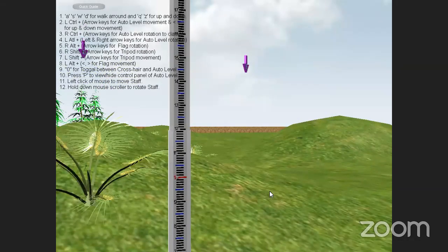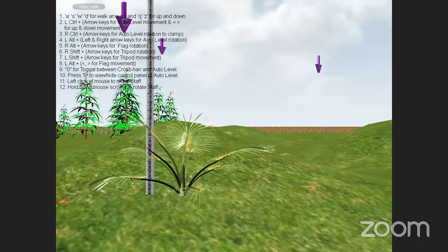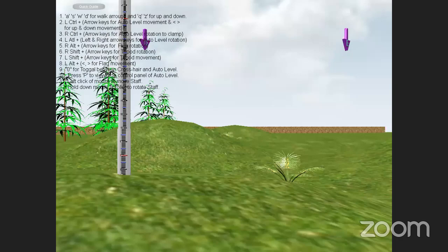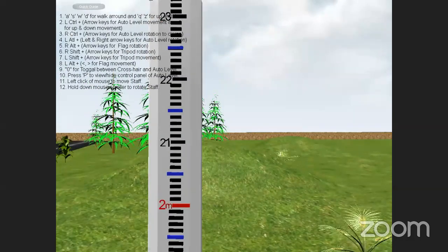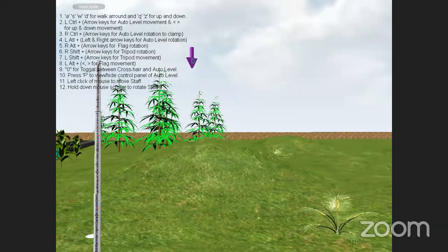Actually, in the actual site conditions, we will be approximately knowing whether it will be visible or not. Manually, you can observe. But here it is animation software. I have to move the staff to C position, then only I will be knowing. And with practice also you will be knowing.